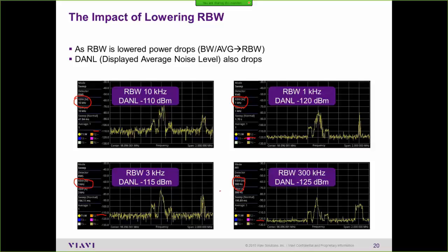So how does that impact making power measurements? If the line on the display is the amount of power in a little bin, then to measure the power of a whole signal, you have to either add up all the little bins manually, or do what you normally would on a modern spectrum analyzer, which is make a channel power measurement.